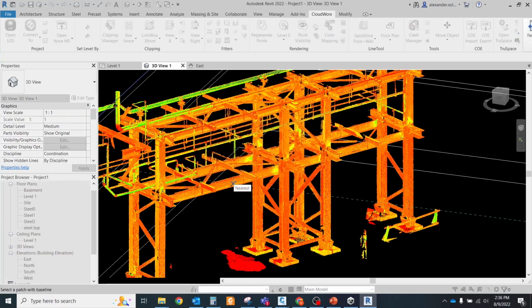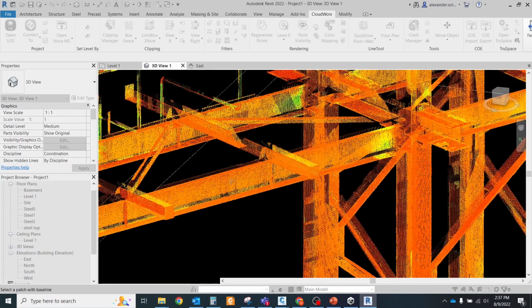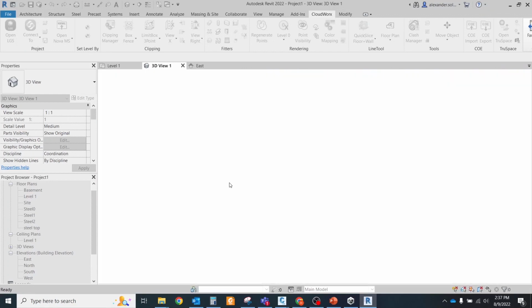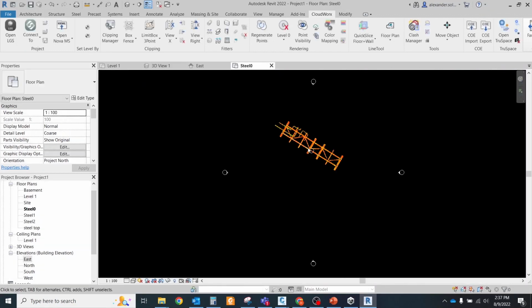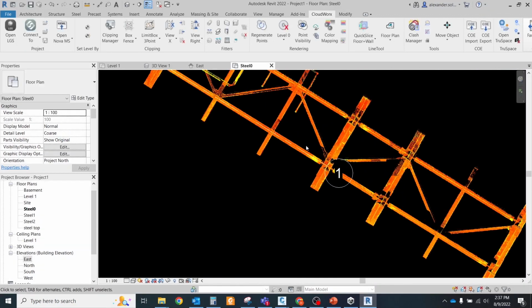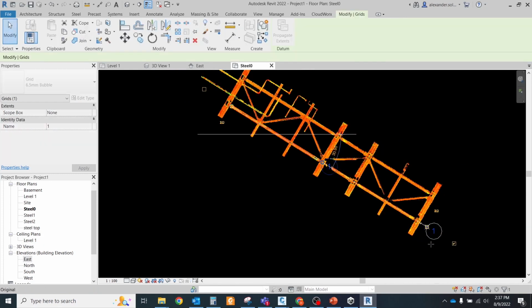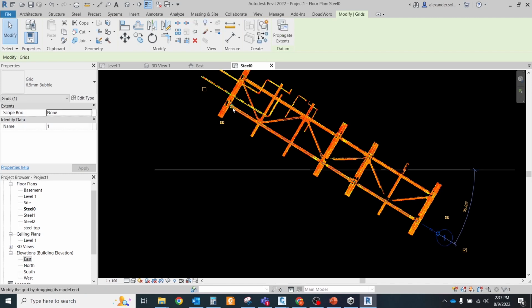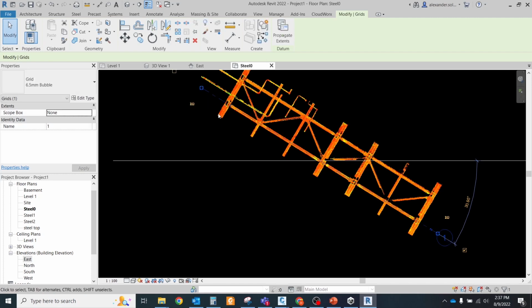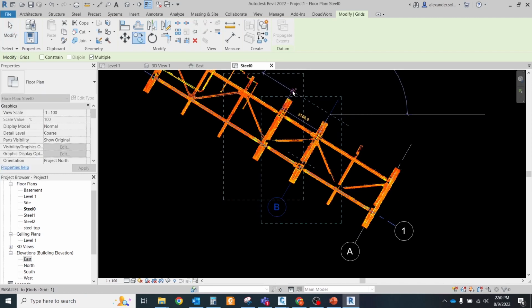As you might imagine, this method doesn't exactly determine the position of the axis because it uses the surface of the element to extract the patch. So the axis will be slightly offset from the center of the steel. This method can be used for some other applications as well. But in any case, it helps us to determine the direction of the axis. Once created, you can move the axis closer to the center manually.